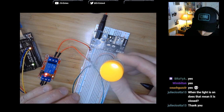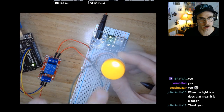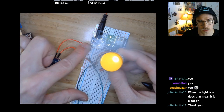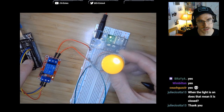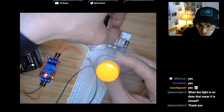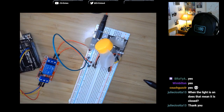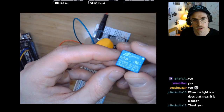So this is the main idea. The Arduino can't provide the power that's generating this right now, but this power supply over here can. So the relay is like the middleman that allows the Arduino over here to send commands that turn it off and on. Okay, so I'll turn this off real quick. Now the cool thing, even though this relay is pretty small, flip it over.